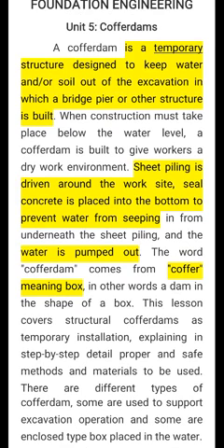Now how are they constructed? They are constructed by means of sheet piling. That sheet piling has to be driven around the work site and sealed with concrete at the bottom, so that water cannot seep in from the bottom.